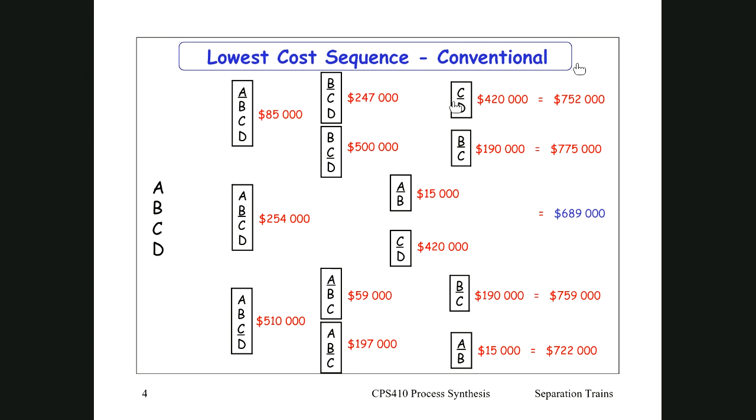There's the direct sequence. Indirect sequence will be over here at the bottom, and then the in-between methods over here, and then you can separate it right down the middle, and then you'll have 2 binaries. So these are still 3 distillation columns that you need, and you can work out the total cost of all 5 of those sequences. Here's the middle sequence, that's 1 sequence, 3 distillation columns. Here's another sequence of 3 distillation columns, and you get the totals, and you can just see what is the cheapest. Okay, so there you've done your optimization.